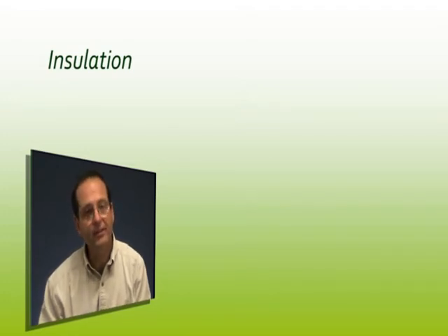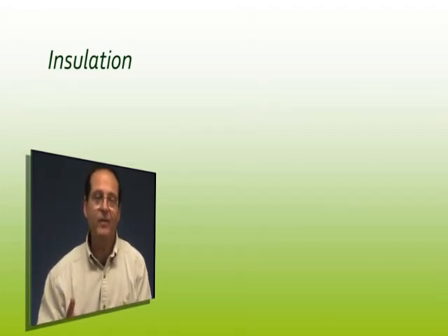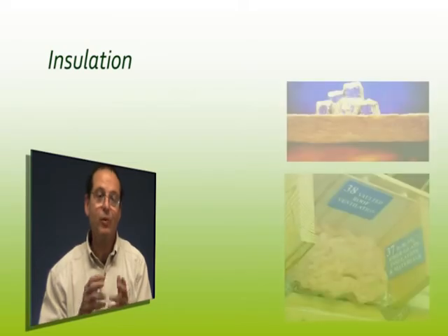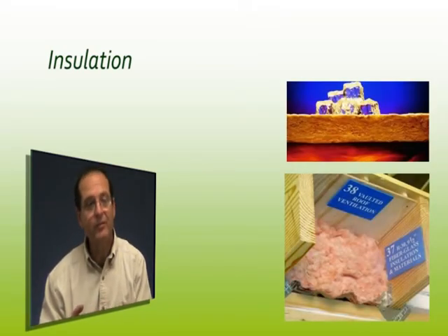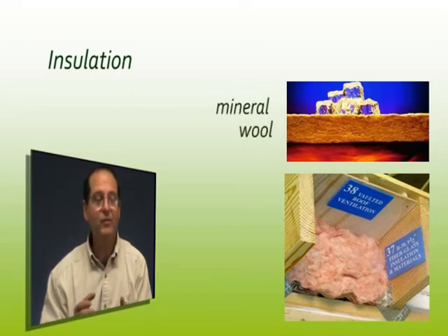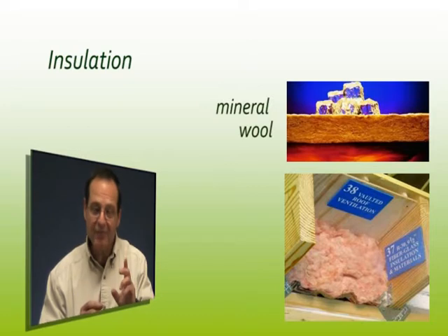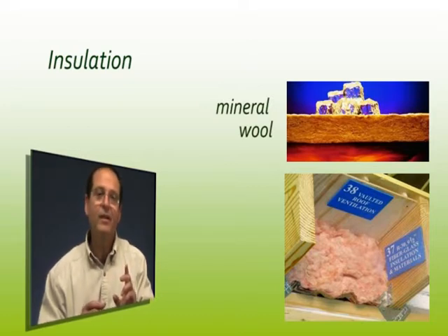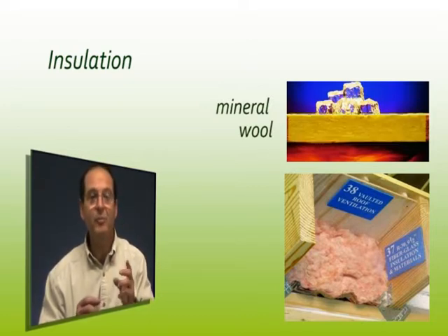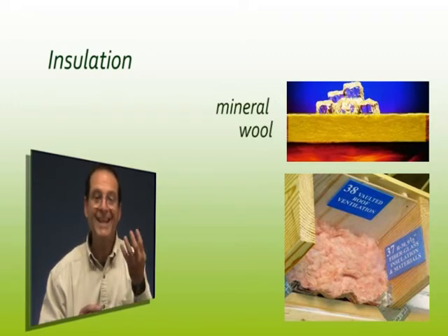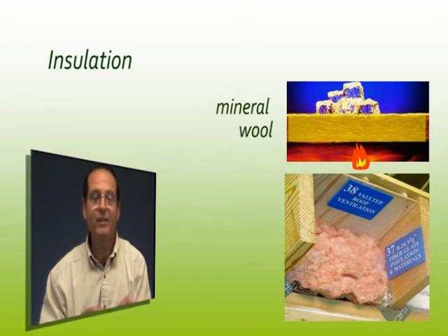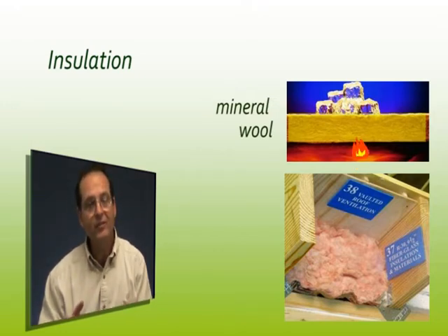Then there's insulation. Again, very specific. This particular system is mineral wool, and it's got to be 2.5 pounds a cubic foot. There's a couple different weights and varieties here, but as you can see in this picture, it's much more condensed. It's typically a thinner batt, maybe a few inches at the most, it's more dense, and it actually has the ability to prevent fire from coming up through the structure and from heating the elements above it and raising the heat. Common insulation, fiberglass insulation, doesn't cut it.